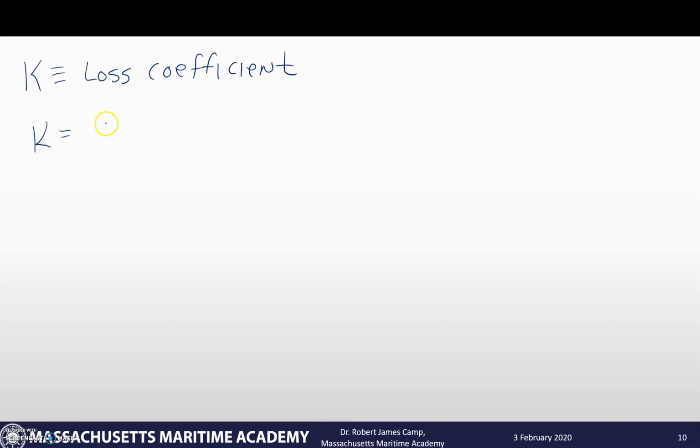So in equation form, what that means is we're going to look at the pressure drop in our device minus 1/2 rho v squared. So you'll see this a lot, especially when you do the lab. There will be a pressure tap at either side of the minor device that we're looking at. You'll measure the pressure loss between the two of them. You'll be able to calculate out the velocity through there, and then you'll be able to say what the K value of that device is.